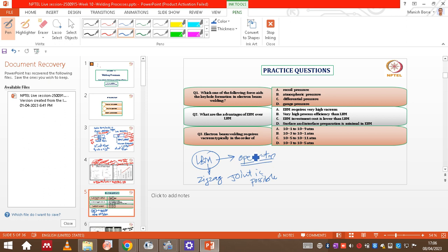Because of that, the efficiency of the process is not that good on certain materials like aluminum alloys or silicon, right? This problem of photon absorption is overcome in another power beam process, which is what we are discussing, electron beam welding.